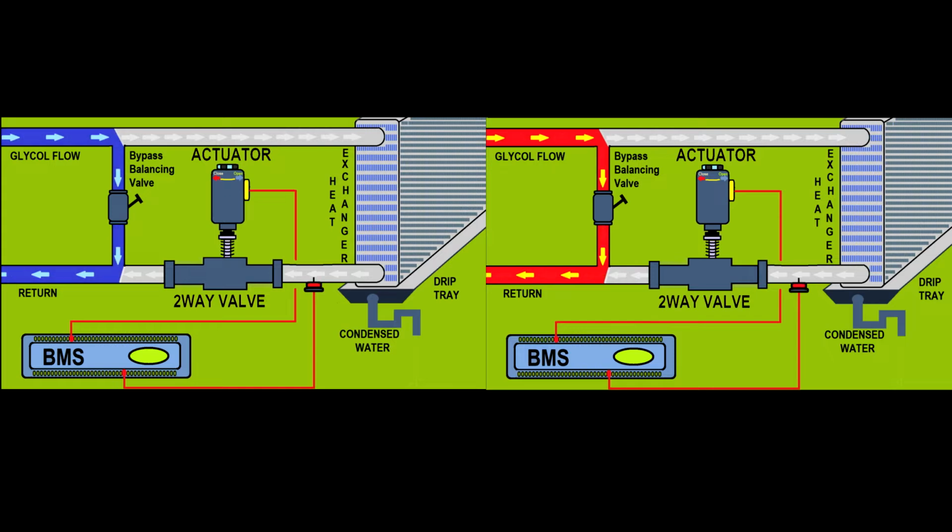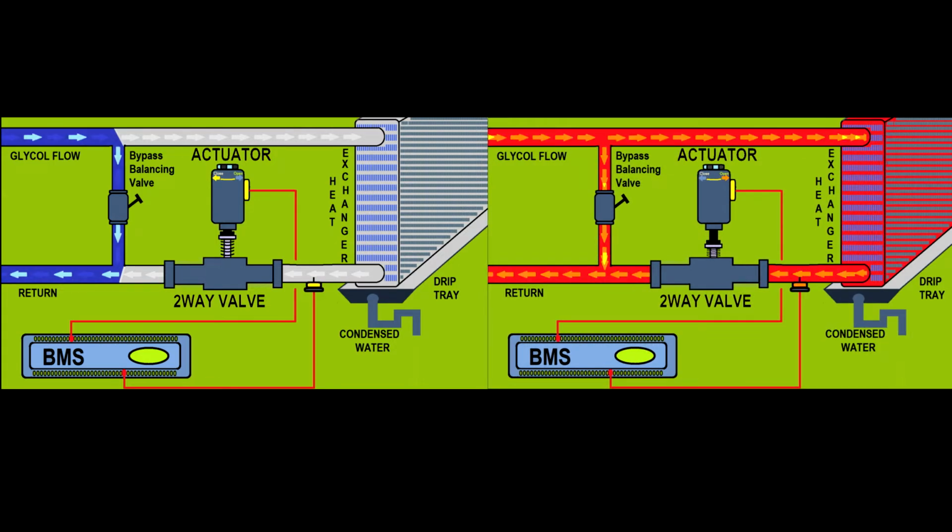When the cooling reaches the set point, the cooling heat exchanger will again be put on standby. If you observe that the cooling agent is not passing through the cooling heat exchanger, the actuator acts on the valve, and the valve restricts the cooling agent from passing to the heat exchanger, and then the room will not cool anymore.